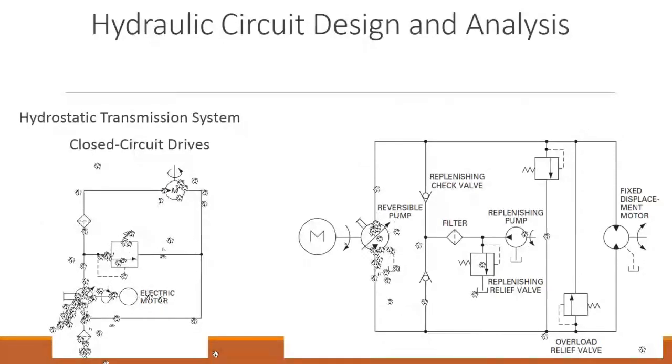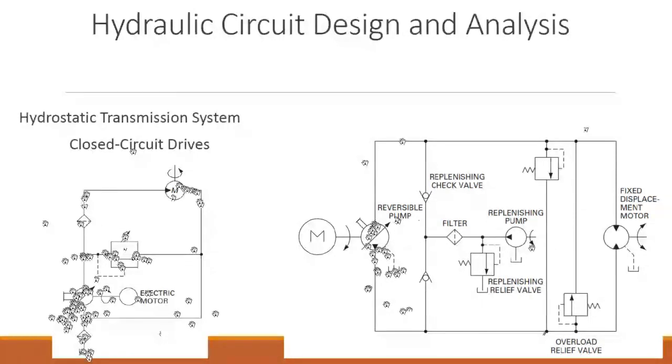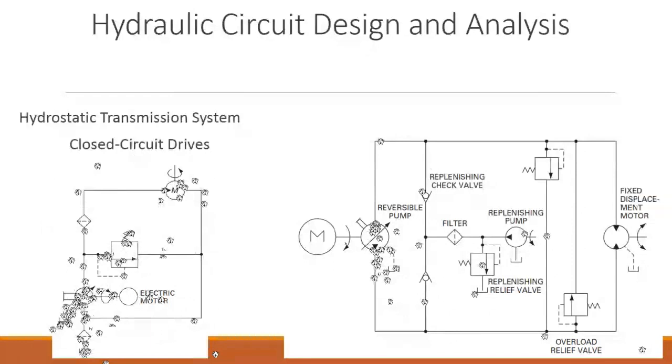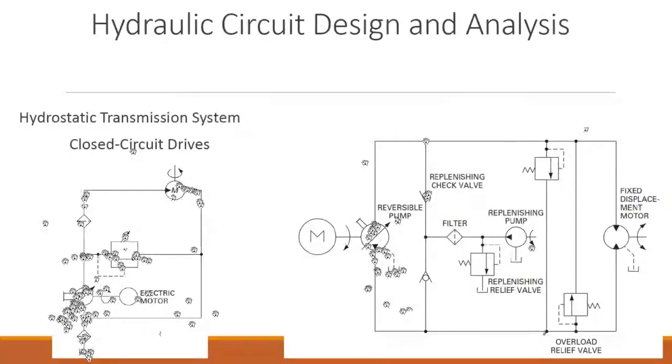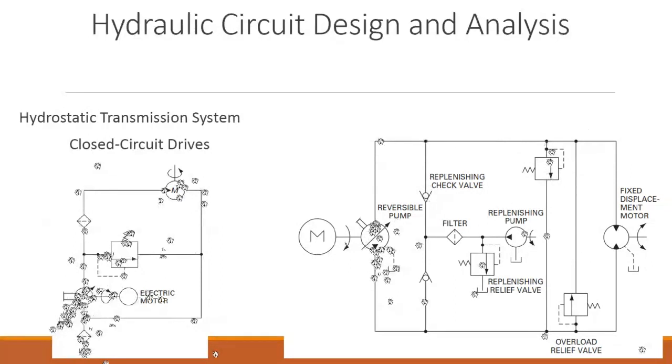So it's a reversible pump. First cycle, which is taken as the oil being pumped by the hydraulic pump in this direction. So it goes up, goes here, comes here again. Check valve, no problem. Everything is closed, so oil will not go here. Oil will go here.